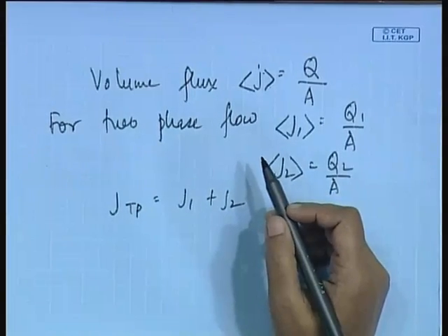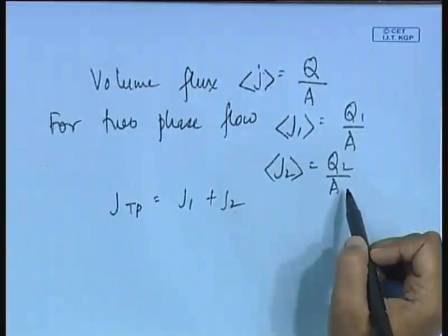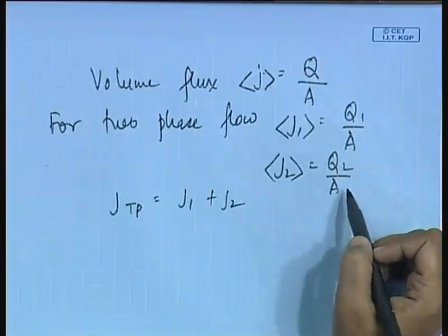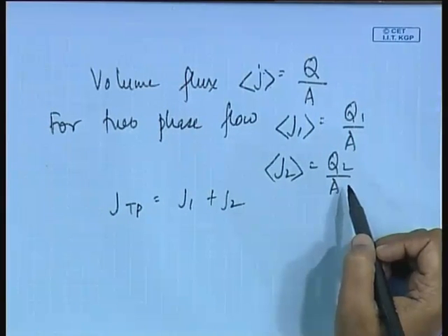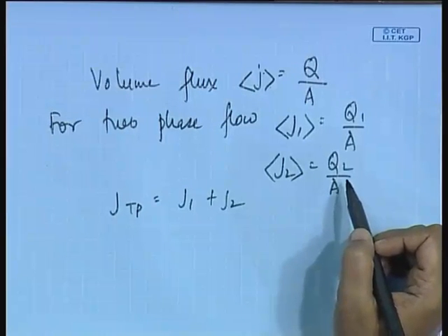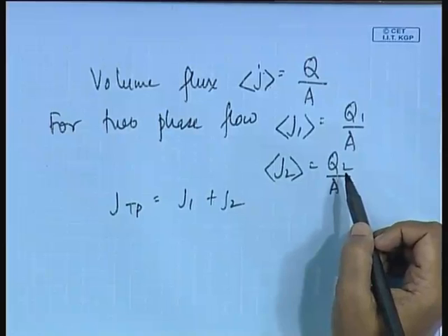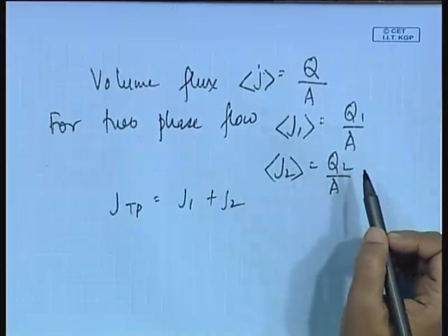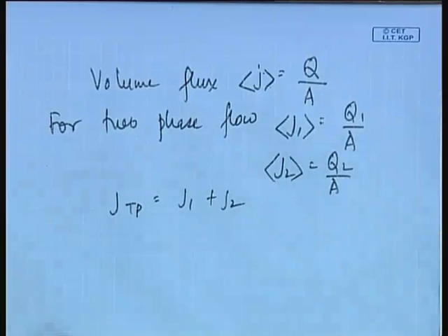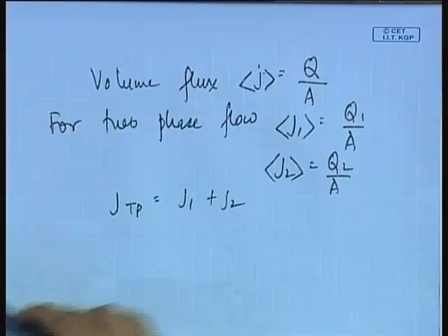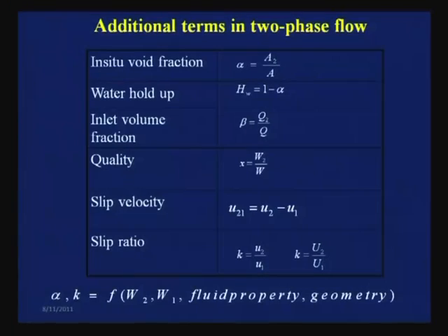One more thing, I had expected this question from you. If you see the definitions, you will find that they are similar to the definitions of superficial velocity. So you can ask me what was the need of defining volumetric flux and superficial velocity. Remember, when we are considering one dimensional steady state flow situations, both of them are the same.